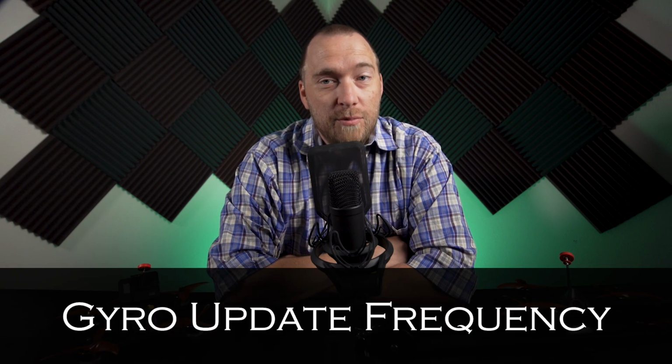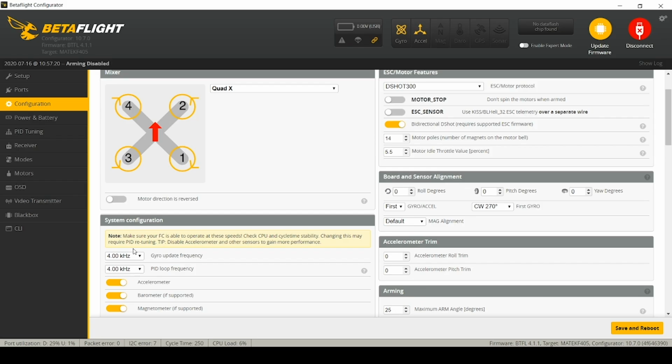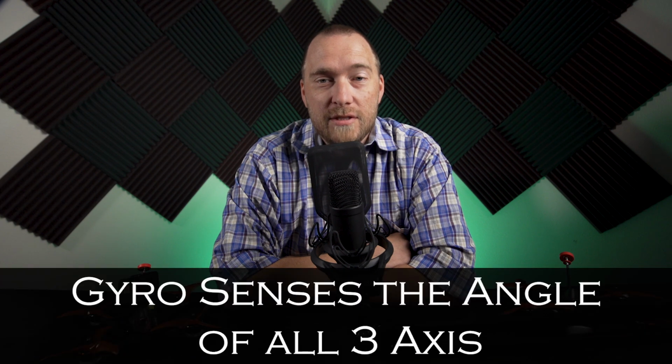You can choose what the sample rate will be in your flight controller software, commonly set at 2K, 4K, or 8K, meaning 2,000, 4,000, or 8,000 samples per second. Generally, a higher sample rate is desirable, but depending on how you set up your flight controller, it might be beneficial or required to lower the sample rate. Like if you're using RPM filtering, you will need to set the sample rate depending on the speed of the flight controller processor.